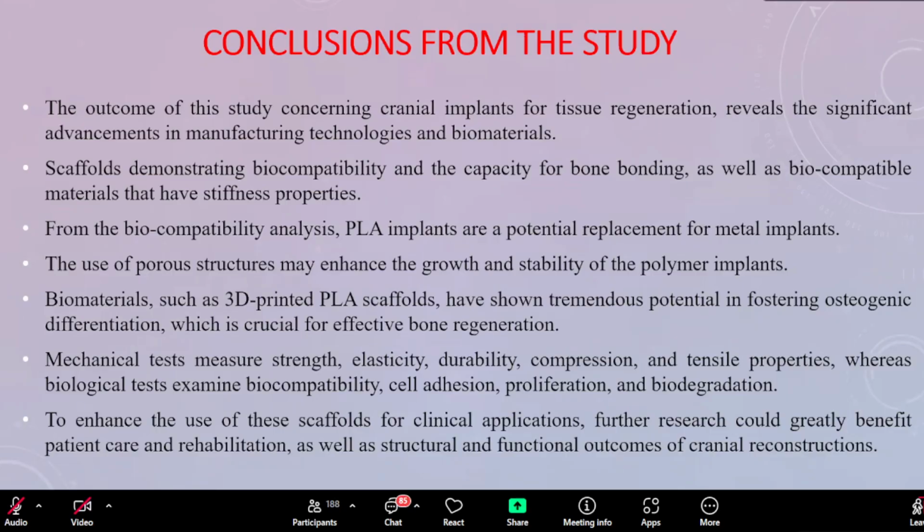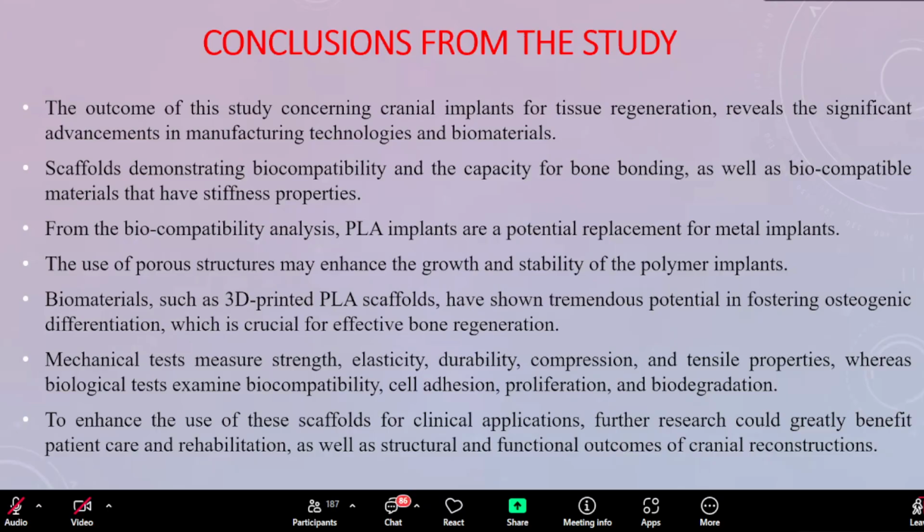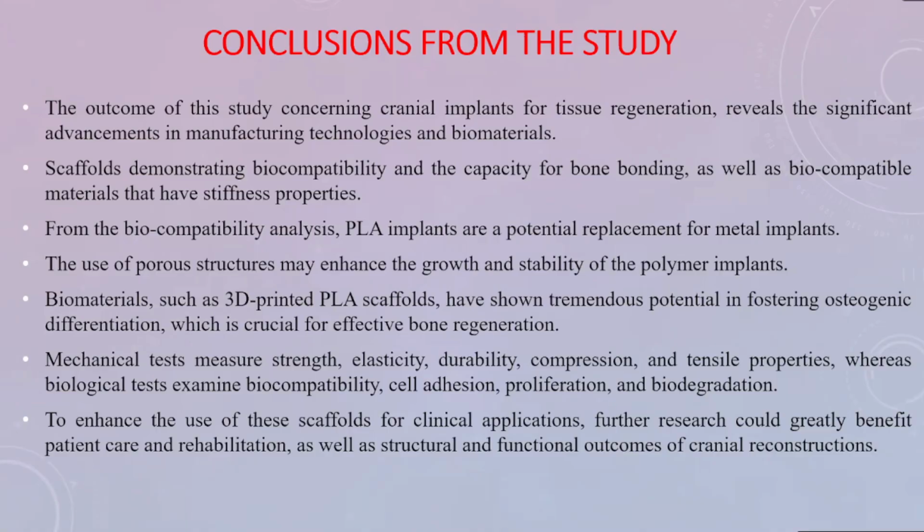Some implants are for critical surgeries where the implant needs to be in place for almost years, for scaffolds which need to grow for completely replacing the skull where there is no presence of bone. If there is a partial presence of bone, this kind of application will be useful. If there is a complete replacement of the bone in that particular skull with the help of scaffolds, I would suggest going with metal implants like titanium, which is costly. Or if you want a cost-effective option in metal additive manufacturing, I suggest stainless steel implants.